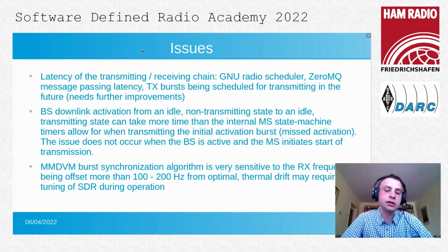The burst synchronization algorithm, which searches for the sync pattern, is quite sensitive to the receive frequency being offset more than about 100 or 200 hertz from its optimal frequency, which means that thermal drift of the software-defined radio may require tuning of the SDR during operation in order to continue to demodulate the transmission.